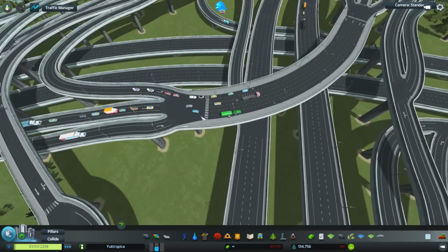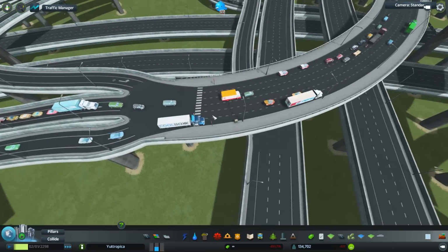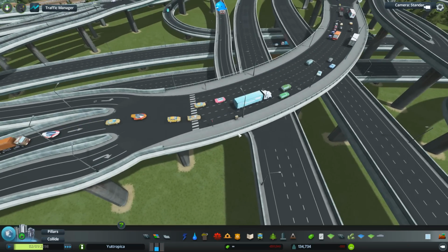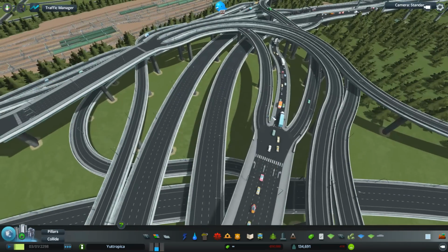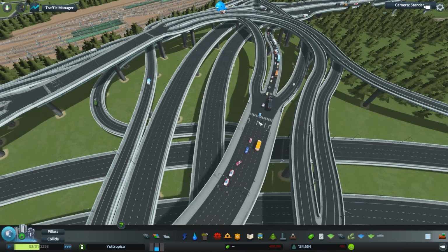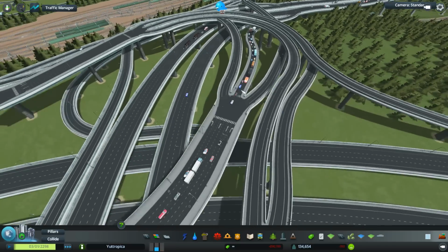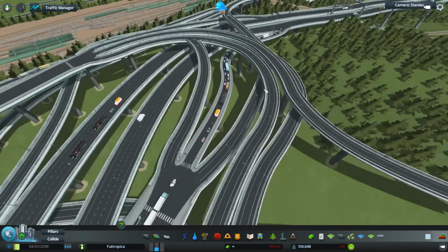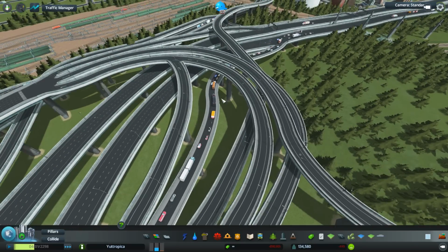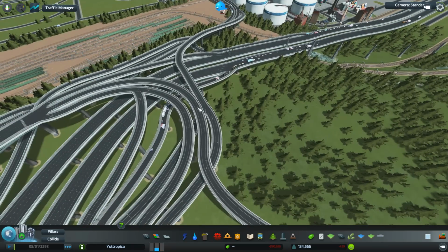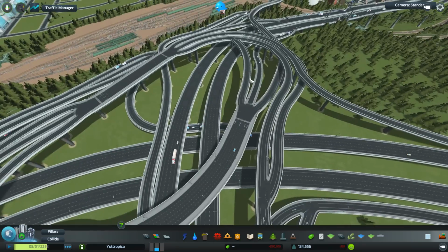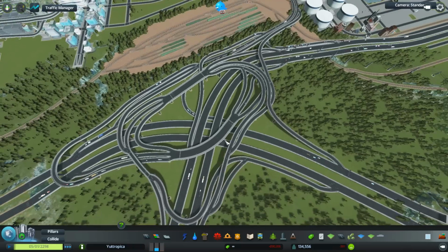I mean, we'll probably get a little bit of backing up here, because this is the part I'm talking about, where the cars start weaving. You have 3 different flows of traffic that merge together and then split off again. But as I said before, the majority of the traffic tends to go through the middle because they're trying to exit off into this. So that's why I added another lane, making this a 2-laner, and that really relieved a lot of stress off of this whole thing.